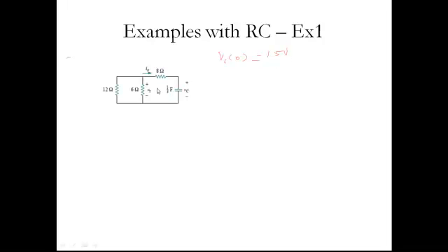So now the first thing you need to understand is, in this given circuit, you are not having any external sources. No DC sources there. So what will happen? The capacitance initially is at 15 volts. It will try to dissipate energy. It will try to drain all its energy through this resistance, and the resistance will dissipate all the energy. Okay. So that is the nature of the RC network without sources.